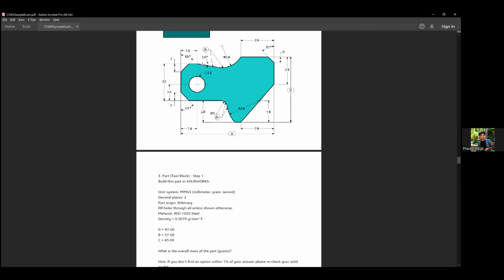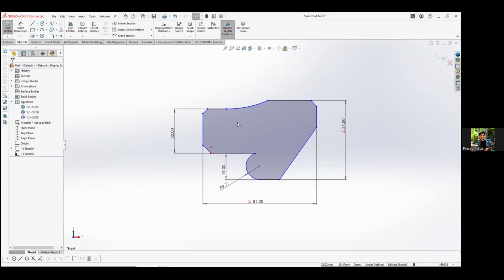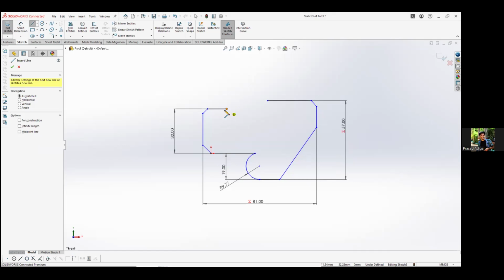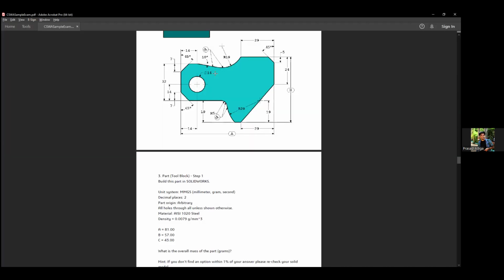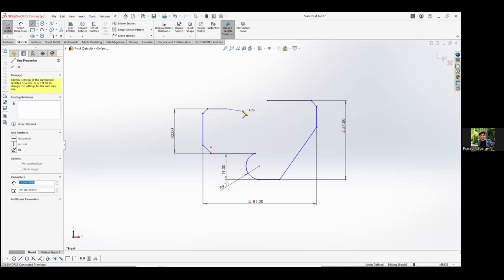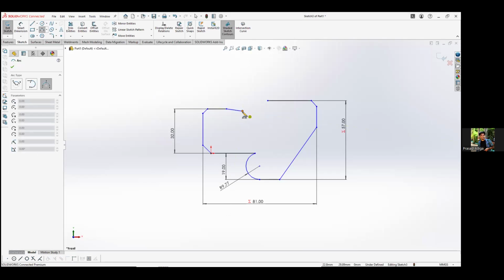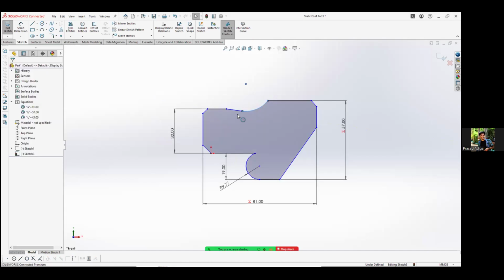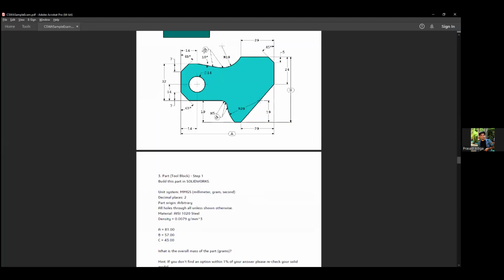And the next is there's a 10-degree line here. Our curve is not exactly the curve we want. We should drop to 10 degrees, and then the curve starts. So we'll just draw a small line and then take this arc and leave it at that. Make sure, as you can see here, there is a tangent direction, which means this line and the curve are tangent to each other.